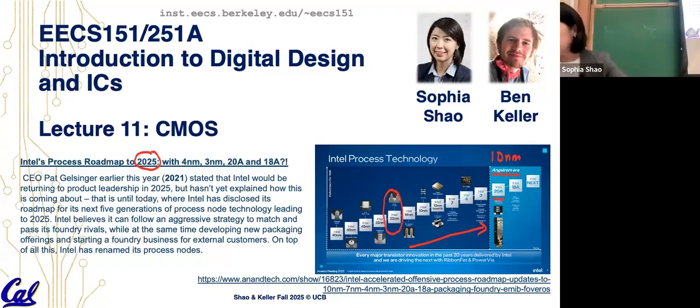Back then, Intel introduced two very significant changes. We'll talk a little more when we get to the lecture. One is migrating from FinFET to what they call RibbonFET, or what some other people call gate-all-around. Instead of just fins, you can create almost circles wrapping around the gate, to have better control over the channel. That's one of the very significant changes since the FinFET generation.